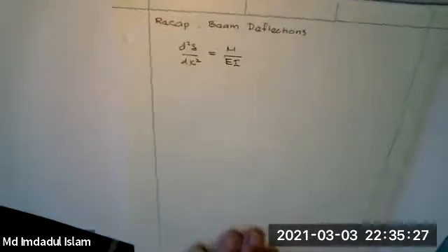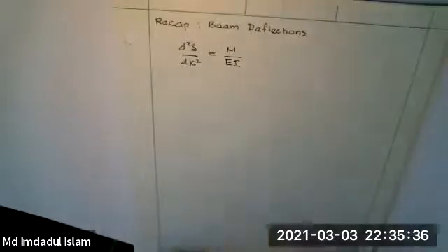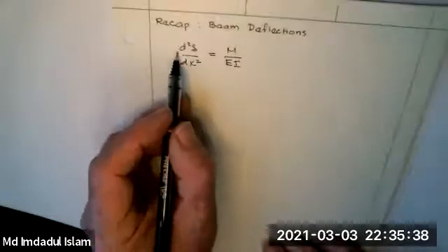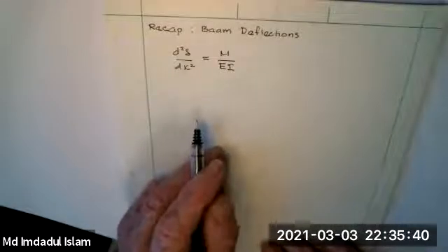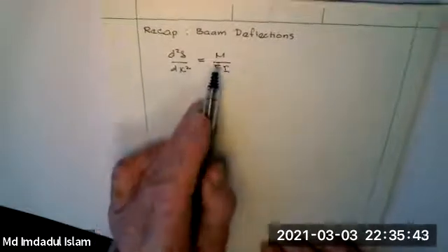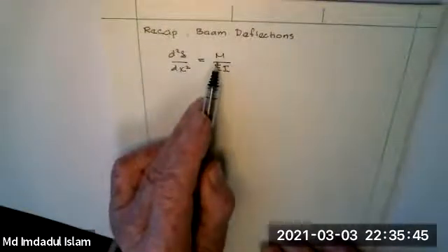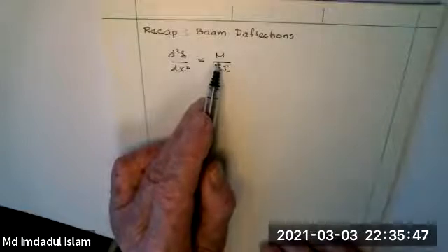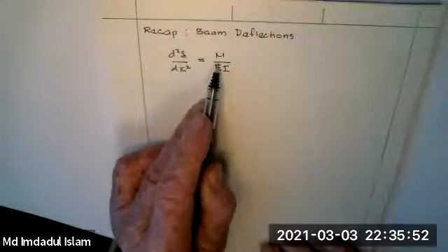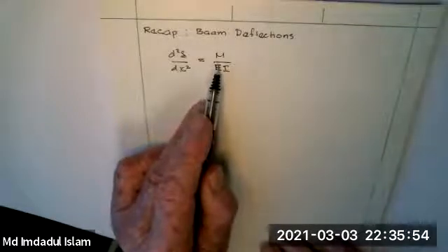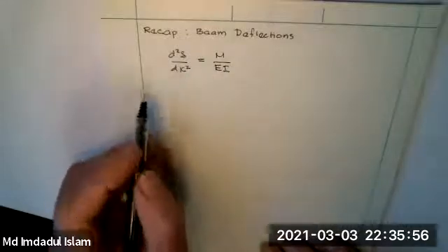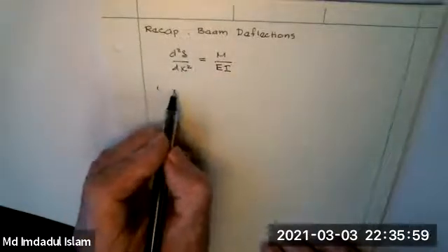So we want to get beam deflections. Sometimes we want to get them just because we want to know how much stuff deflects. Quite often we need to get deflections to solve statically indeterminate problems. Very common. We're going to focus on using the second order ordinary differential equation, because one of the things we're always going to want is M, this bending moment, because that's the principal thing that leads to bending stresses. Okay? And bending stresses, as I've shown you, are much bigger than the shear stresses in the center of the beam. So the approach here has 3 steps.